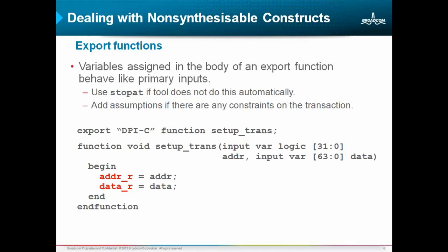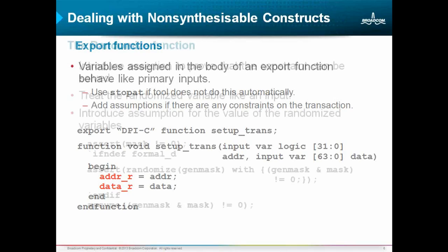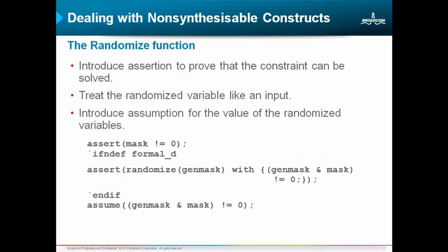The other one is just in some places you do end up putting non-synthesizable stuff into your synthesizable parts of the design because you'll get more control in simulation than you will in emulation. So, for instance, you might be randomizing something in simulation where you'll hardwire it in emulation because you're really not so bothered at that point. So occasionally you'll end up with randomized functions here, which obviously don't work well with formal.